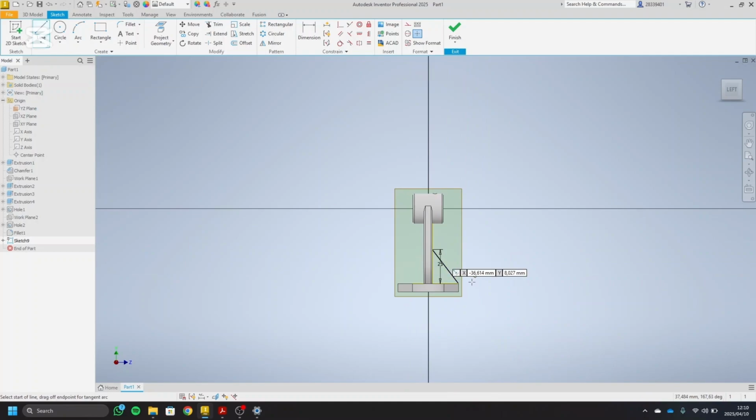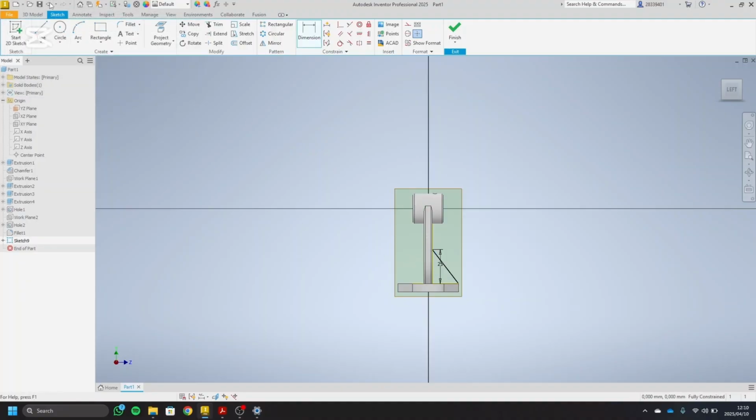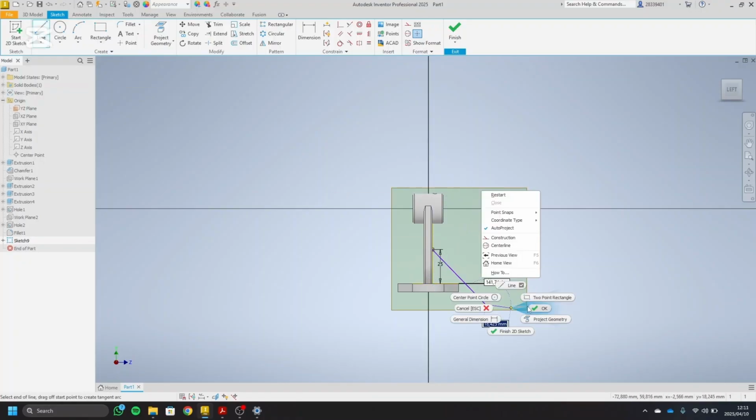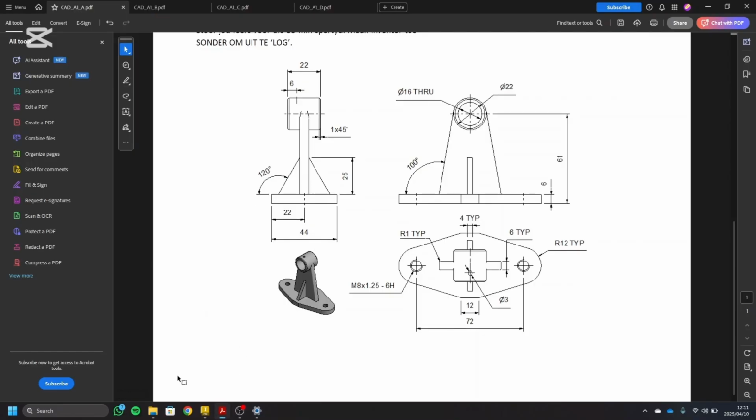And we can just make sure, just create a straight line out, and we can dimension here to here, that should be 120. Okay, so just create a line first, and then we can take a line from this point, just plot it over there, and then we can dimension this to that as 120. I think it should be 120, yeah, 120.